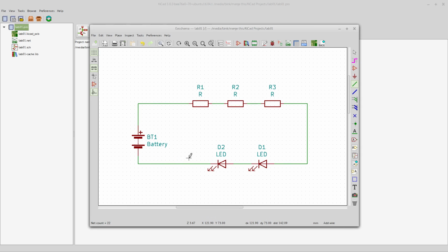That might bite you down the road if you think that you don't need to do it because it's seemingly such a small change, if you've misunderstood what a net list is doing and you think that maybe it's just the connection of LEDs or all the components together, but it's not necessarily the documentation or something like that, well, that would be incorrect. Anything you do back here at the schematic, just like you'd hit save, you generate a new net list. Okay? So now that's done. We can close this. I wouldn't recommend doing this though because you're probably going to be back. It's not a big deal. Nothing's going to break. You just got to open it back up.